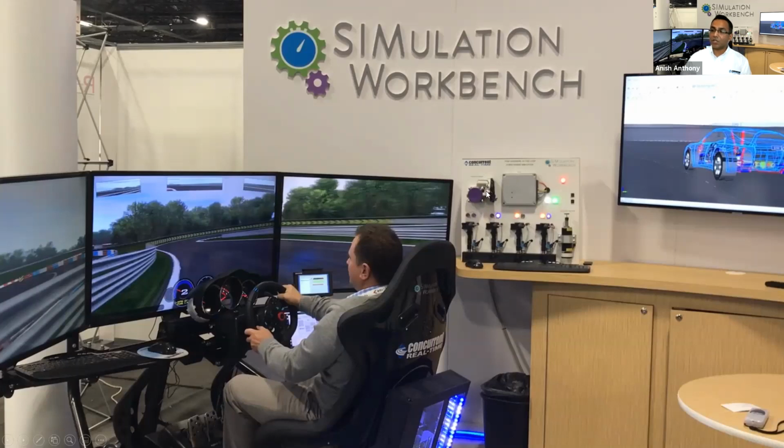You see ignition, injection, a throttle body, and an electric motor, because we are simulating a hybrid vehicle, and all of that is connected to this computer. The ECU thinks it is talking to a real car because all the sensor signals it gets from the real-time computer and the model make it believe that. This is the way they test models in real time, especially in Formula One racing. The tracks change, the cars change, the settings change every race, and they have to be very quick in prototyping and testing with the hardware-in-the-loop setup.